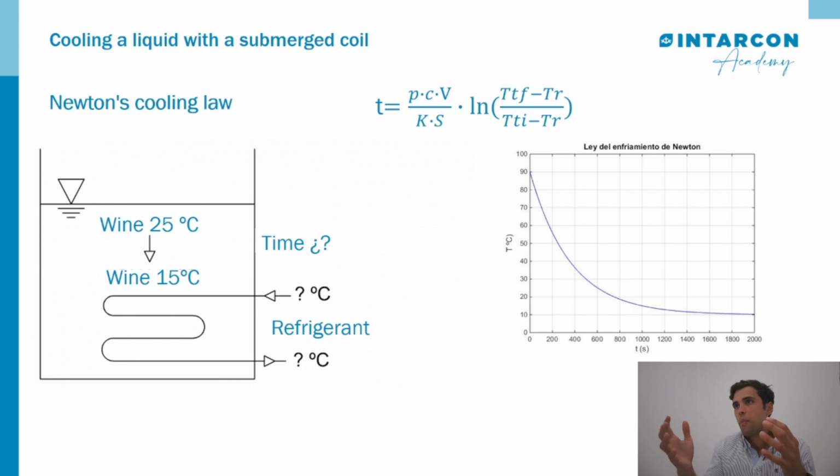This system is apparently the most economical in terms of installation, and only requires a coil that is submerged in the tank. However, we have disadvantages for the space in the tank and the space of the coil, and the heat transfer that we are going to have in this system. That is a big drawback.